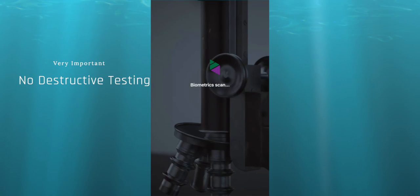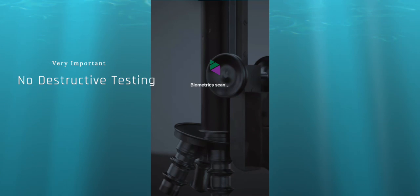If you are an insurance adjuster, it is not recommended that you perform any type of destructive material sampling. What I mean by that is that if the material in question is still in its installed state, do not cut, nor remove, nor displace the material just so that you can perform this material sampling. Because the only damage that may exist on the lost property may very well be the damage that you may have caused by removing this material from its installed state.